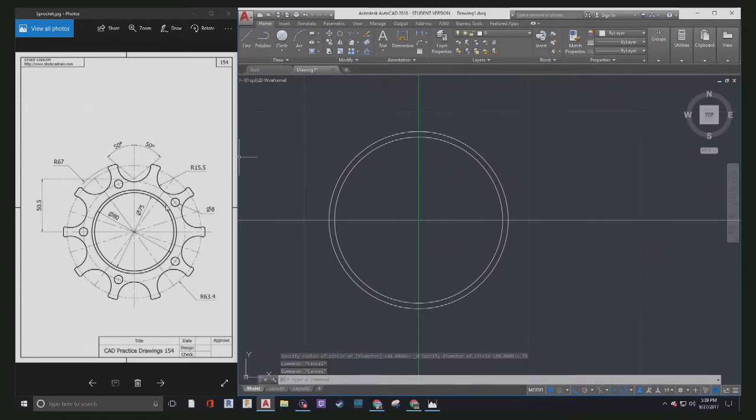There's going to be a couple more. The other circles I'm going to identify right now is this guideline outside circle that's going to define the center point of these circles that are cut out around the outside. So I'm going to do that with the guideline layer, and we're going to do that at an outside radius of 67. So let's do that.